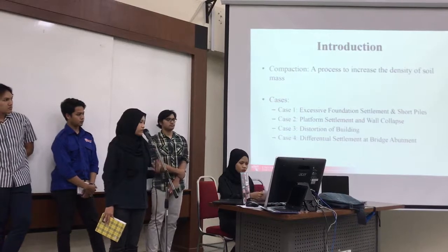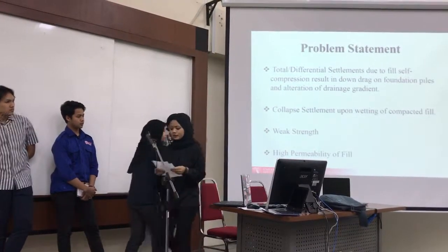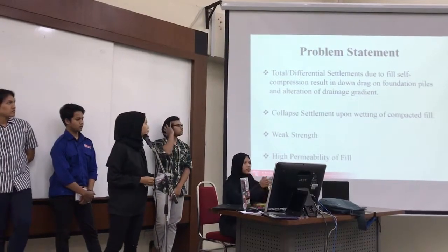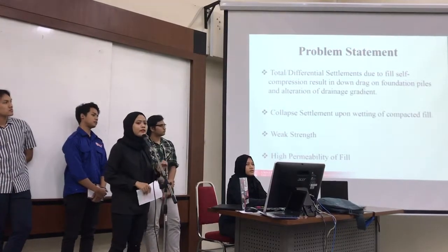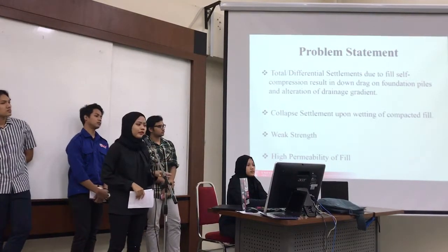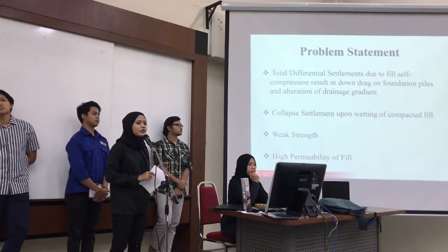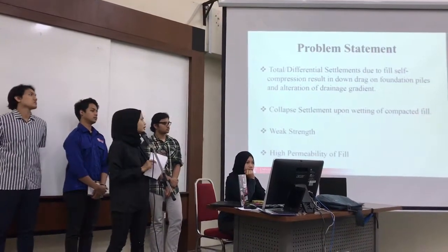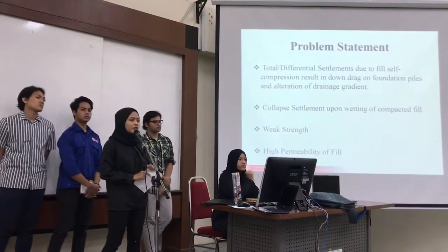I will pass to my friend Syamimi to explain the problem statement. Thank you, Ain. So I will explain more about the problem statement. We have already identified the factors that contribute to the failure of this project, which is the total or differential settlement due to fill self-compression, resulting in the downdrag on foundation piles and alteration of the drainage gradient.